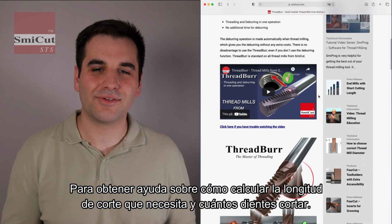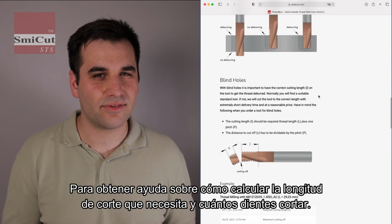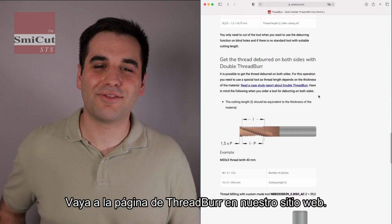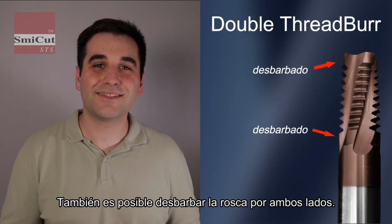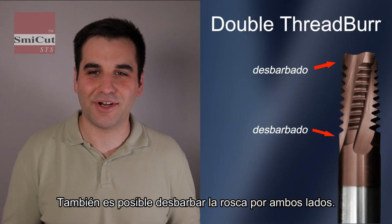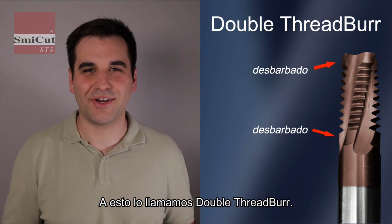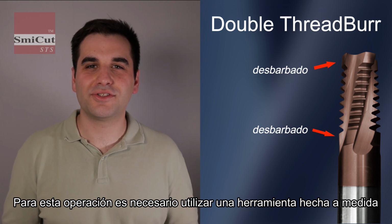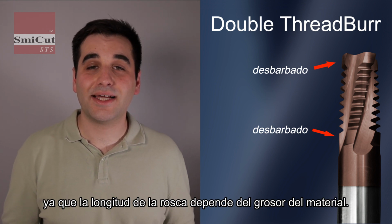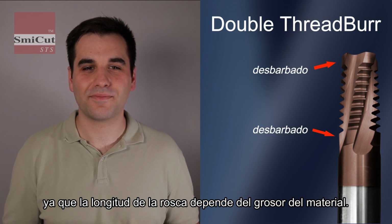For help on how to calculate the cutting length you need and how many teeth to cut off, please go to the ThreadBurr page on our website. It is also possible to get the thread deburred on both sides. We call this double ThreadBurr. But for this operation, you need to use a custom-made tool, as the thread length depends on the thickness of the material.